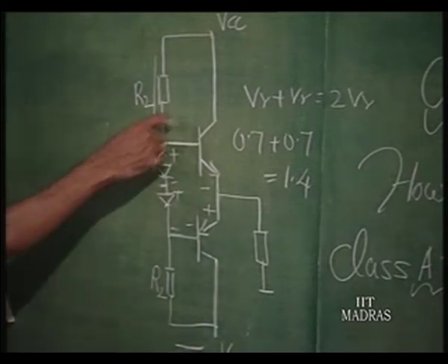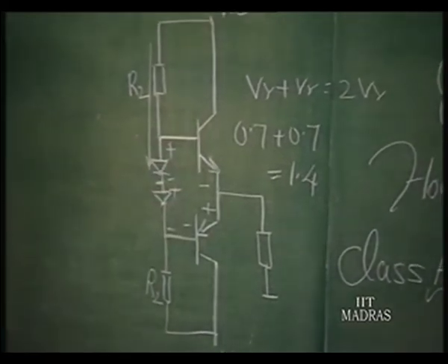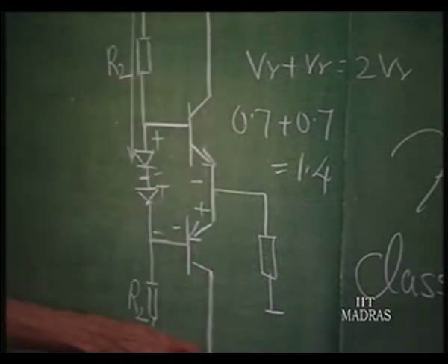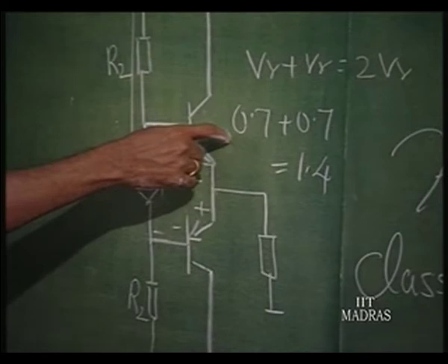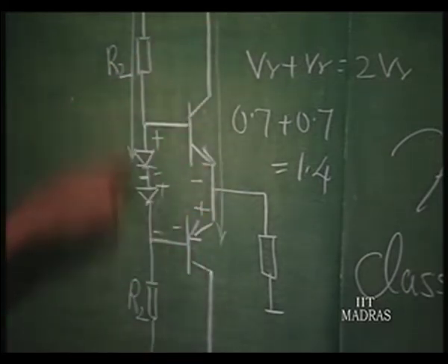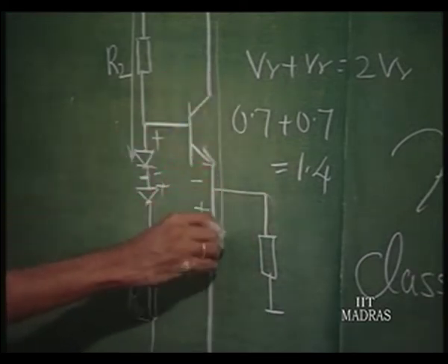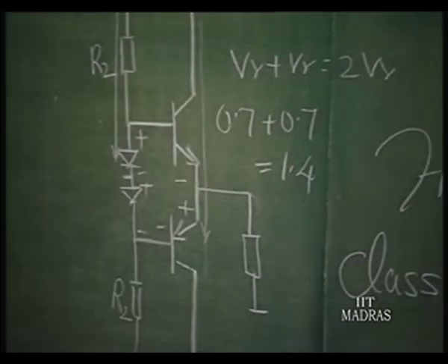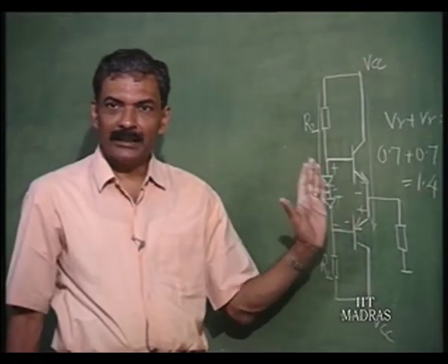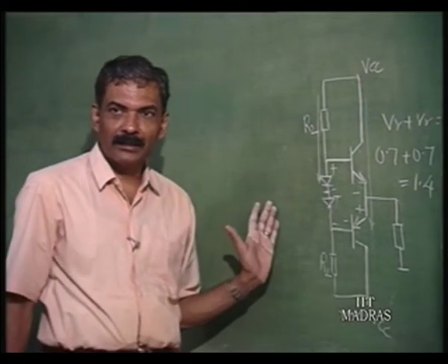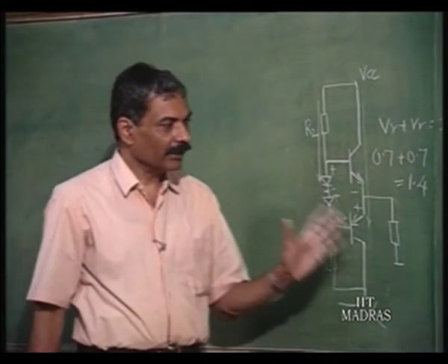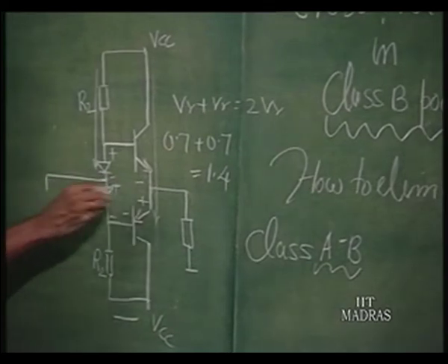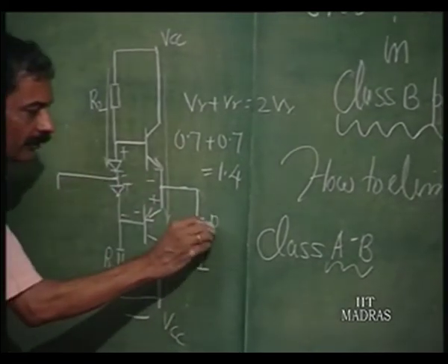If these diode and the transistors are made out of the same geometry, then this current is going to be the same as this current. This is nothing but a current mirror that I had earlier talked about. The load current will be still 0, because this current is exactly the same as this current. Load current is still 0, but you can make any quiescent current pass through the power amplifier, which is quite low. So, it is in readiness to conduct the moment the signal starts coming into picture. So, this kind of class AB biasing is what is normally adopted in power amplifiers to reduce the distortion.